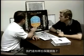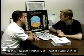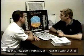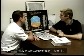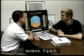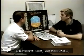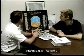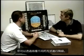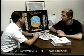What other protection do we have available, for example, G protection in normal law? We have load protection in normal law, and that is 2.5 Gs positive to -1 when we have clean or slats. If we have trailing edge flaps out, that range is limited to 2 Gs and 0. That protection is available in normal law, and it's available in alternate law. Once we get out of alternate law, those limits still apply, but they're no longer protections. How would you degrade from normal law? You could degrade 2 different ways. One is the catchphrase, multiple failures of redundant systems. The other way is by getting into an abnormal attitude configuration.